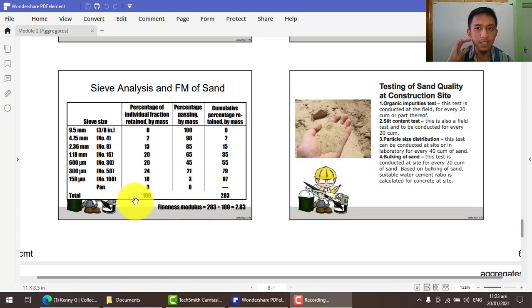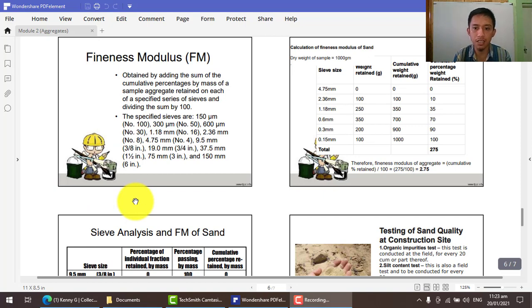Again, as I've explained, silt or clay is not advisable because that will make the concrete mix weaker. It is just like soil. Is soil advisable in a concrete mix? Of course not. As you can see on most construction, no one ever uses soil in a concrete mix. Only, of course, these bigger sizes, fine aggregates or coarse aggregates.